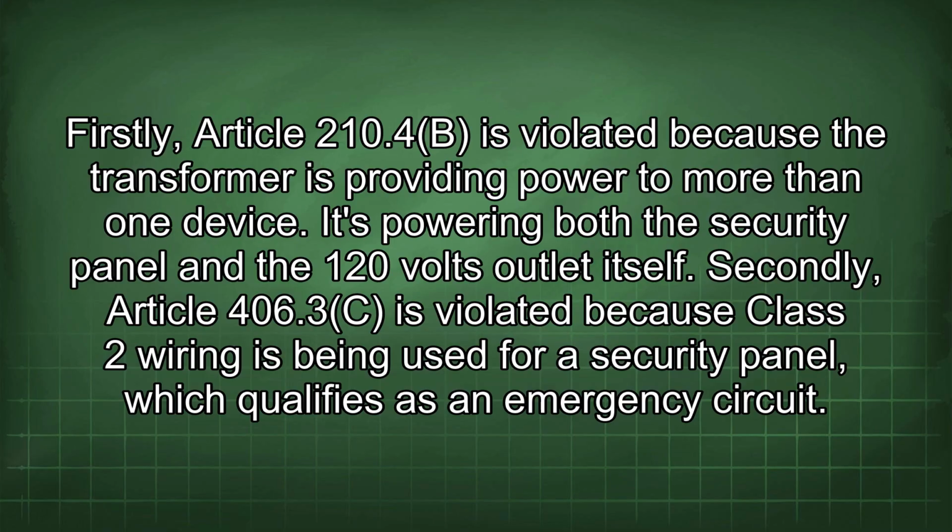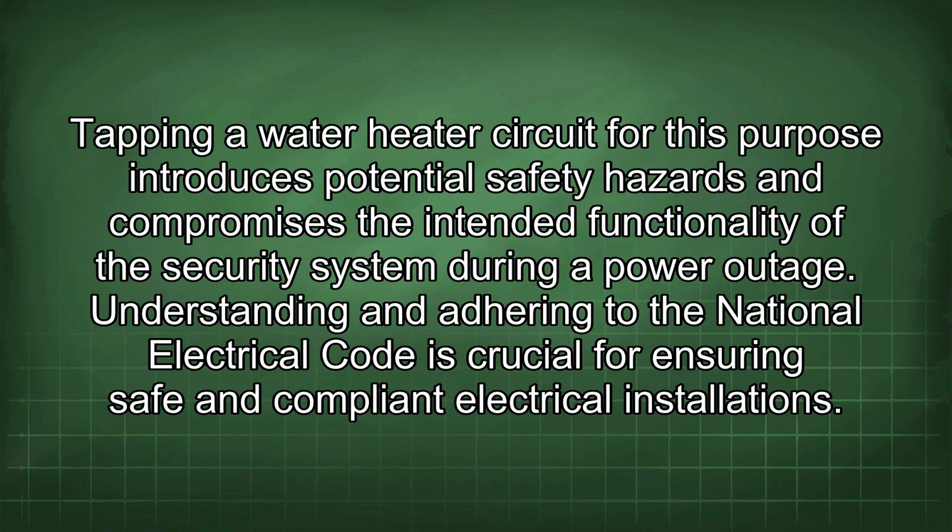Secondly, Article 406.3c is violated because Class 2 wiring is being used for a security panel, which qualifies as an emergency circuit. Tapping a water heater circuit for this purpose introduces potential safety hazards and compromises the intended functionality of the security system during a power outage.